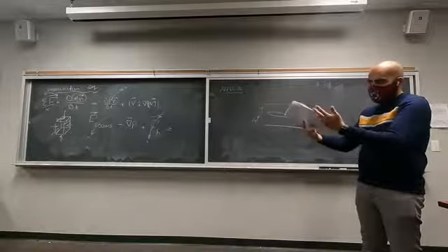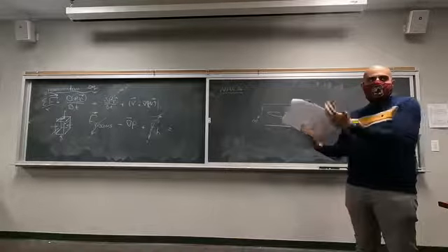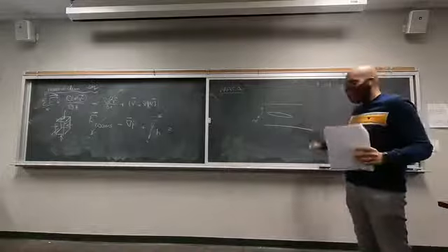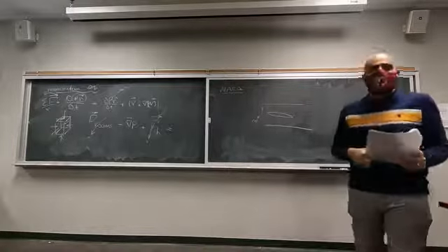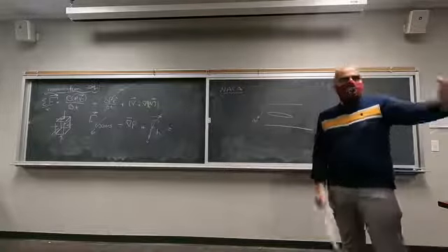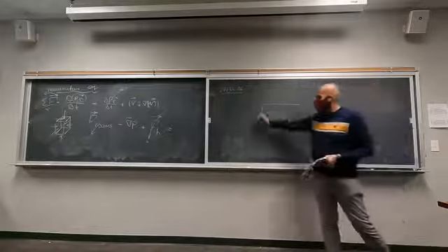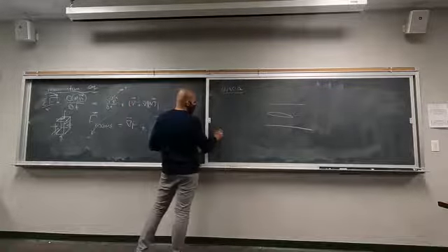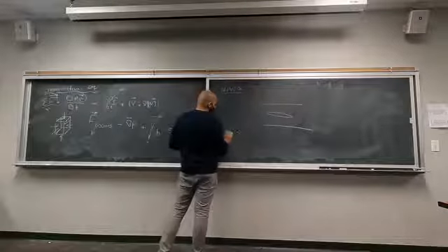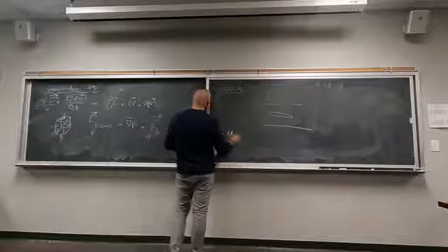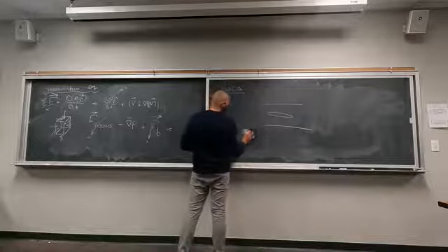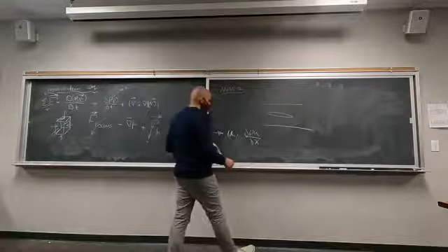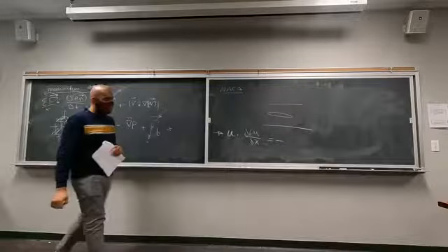So the wind is coming. Let's say I am the wing and the wind is coming towards me, right? They made sure that the wind goes from the wing that they're analyzing, from this wall to that wall. What does this do? It essentially helps remove the three-dimensional effects from the tip of the wing. And we are going to talk about the three-dimensional effects later in the class. So they remove the importance of this and this. So you end up with only one directional momentum equation, which is going to be equal to the other side, whatever that is.